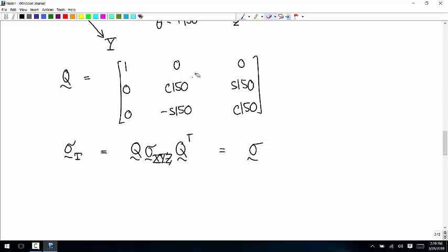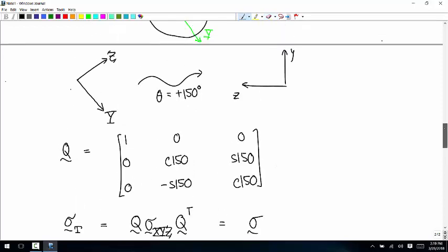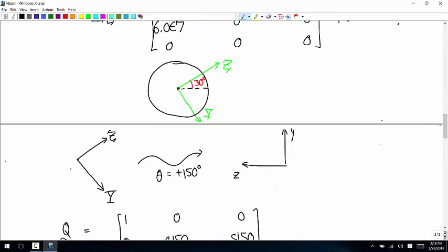Well, actually, in this case, that's a good question. You could just say, in this case, you don't need to. Since the stress due to torque is the only stress on the thing, you could just say, I'm giving my answer in this coordinate system, and that would be okay. But generally, the reason that you have to rotate it is because you've calculated the stress tensors for all your other internal loads using this stress tensor, and you can't add stress tensors until they have the same coordinate system.